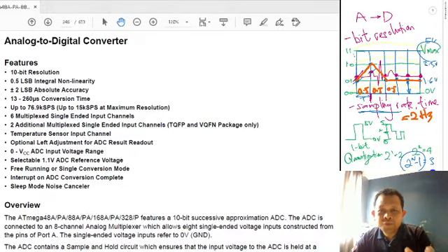So you will need to know what's the best bit resolution and what is the best sampling rate. Just now we talked about a system with 8-bit resolution, 10-bit, maybe 12, we have 16, we have 22, and I think the largest would be around 24, right? So 24 bits means how many quantization levels?